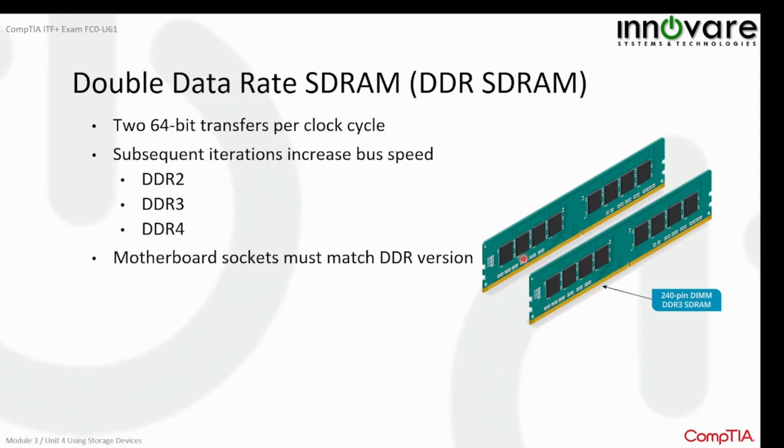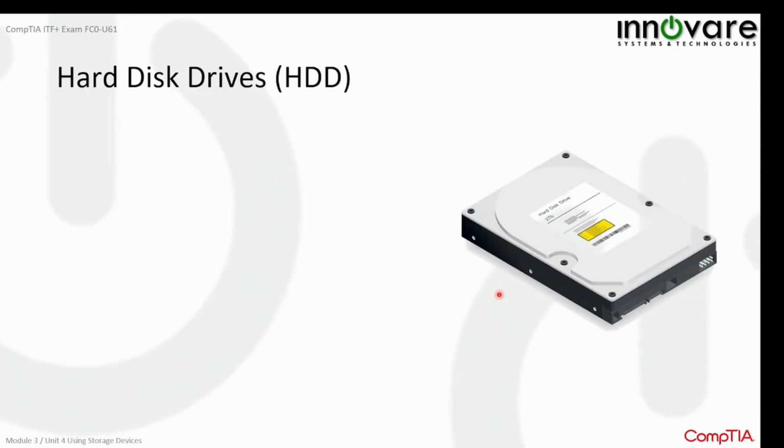And yung tulad ng halimbawa, yung DIMM and yung SODIMM that we mentioned earlier, it has a different pin system. Pati yung notch different then. It will not insert. You will realize that when you try to, sometimes sa akin nangyayari din yun, I'm not paying attention for the type of memory, it will not fit. You will see that it has more pins or the notch itself, hindi siya aayon. Hindi talaga papasok. May purpose yung notch na yan. Etong side na to, that is for interlocking. When you are inserting this memory, it secures the insertion ng memory mismo.